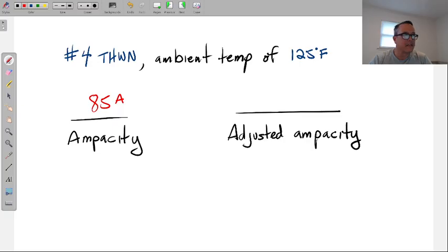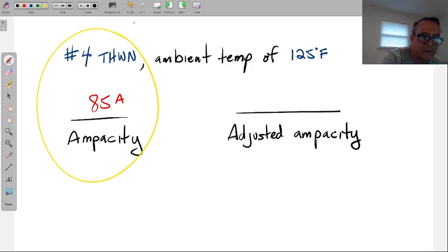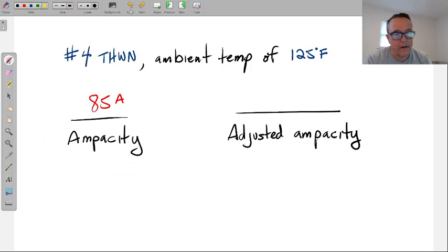And as I think I was mentioning yesterday, maybe I was saying it to the Code A class, there was like a time in the 70s and 80s and 90s where all of these insulation types were showing up. But right now in 2025, we have 2 types, and they're both on the same wire. THHN, THWN-2. That is 1 conductor with 2 types of insulation. And that's 100% what you'll find now. But they're still asking these questions in the code exams with all these different insulation types, so we still have to know how to do this.